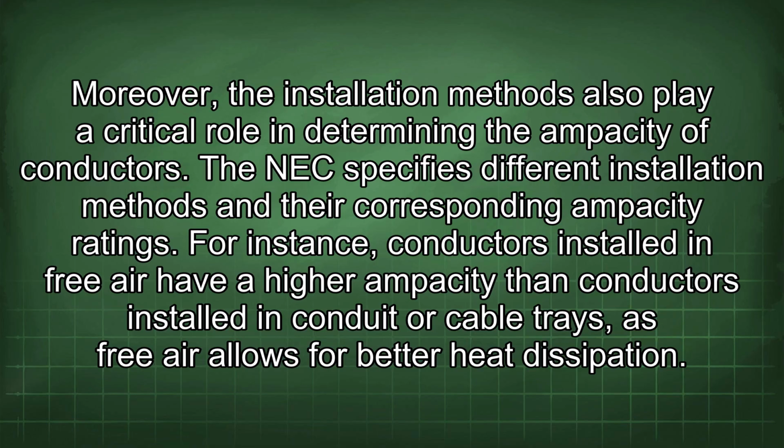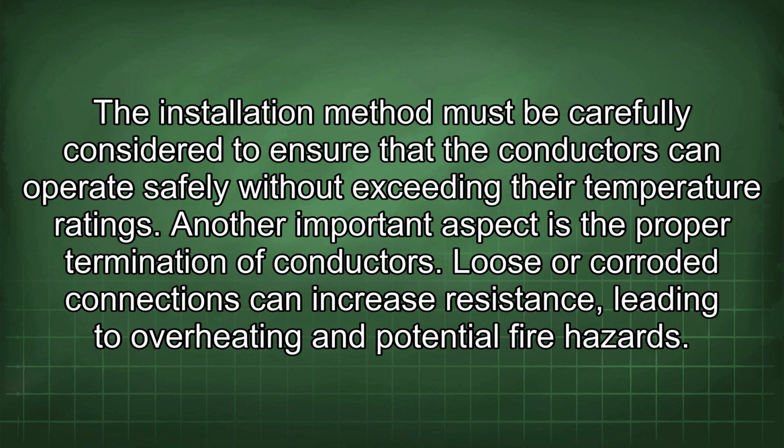Moreover, the installation methods also play a critical role in determining the ampacity of conductors. The NEC specifies different installation methods and their corresponding ampacity ratings. For instance, conductors installed in free air have a higher ampacity than conductors installed in conduit or cable trays, as free air allows for better heat dissipation. The installation method must be carefully considered to ensure that the conductors can operate safely without exceeding their temperature ratings.